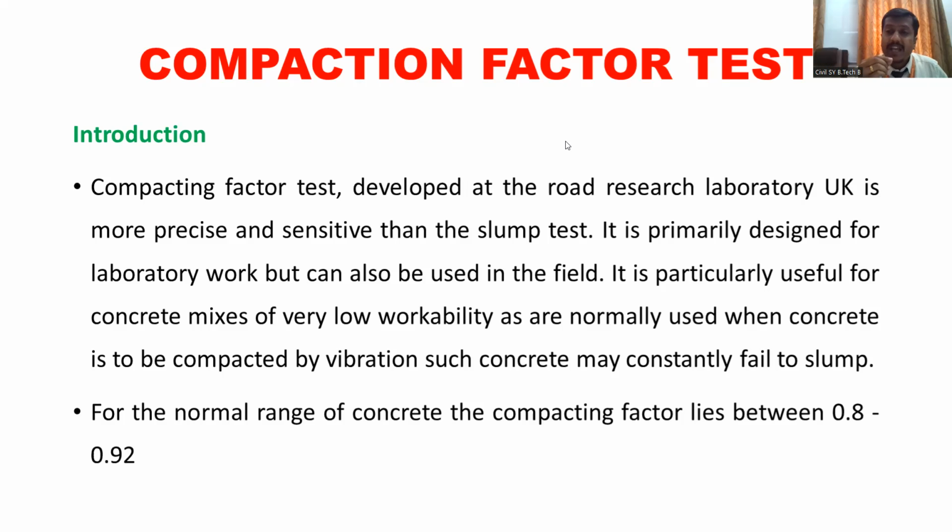ठीक आहे, आता वर्कॅबिलिटी हा शब्द जो मी सांगतोय, ही जी सुटेबिलिटी मी सांगतोय, ही सुटेबिलिटीसाठी आपल्याकडे as per our Indian Standard IS specifications, we are having one table. I think it is given in IS 456. It is given in IS 456, which tells you the slump value, the nature of the concrete. It may be low workable, moderate workable, or highly workable, and the suitability of that concrete to place it in different positions. I will show it to you right now only. Okay, लगेच दाखवतो मी तुम्हाला. I think it is there in IS 456 table number maybe 5. Okay, I will share the new screen. Just give me a minute.